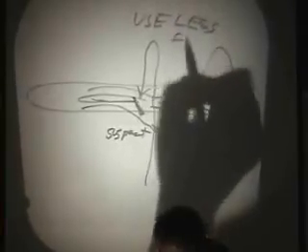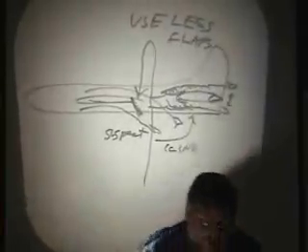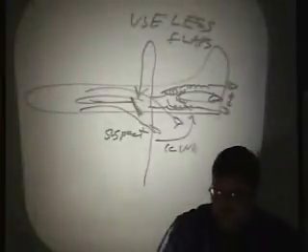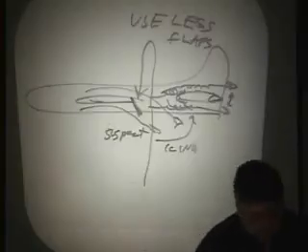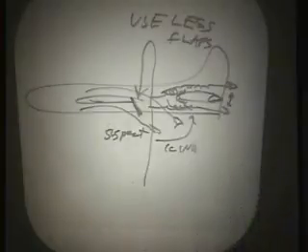then use less flaps. In fact, I recommend that you try to use no more than half of what you normally would. Now, granted, you'll have to fly a little faster on your approach, and you'll touch down faster, and you'll use more runway, but there are multiple cases of airplanes coming into land, and on approach, as they went to full flaps, they lost control of the airplane in pitch because the effectiveness of their elevator was so little that they couldn't maintain pitch control.